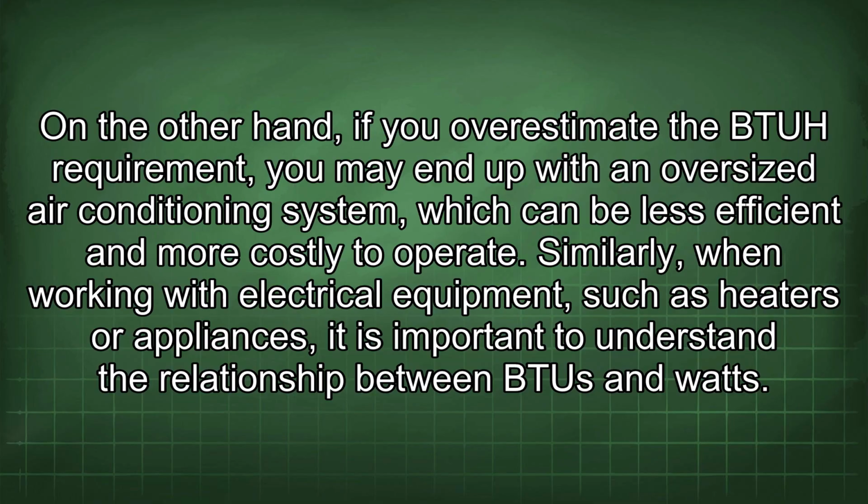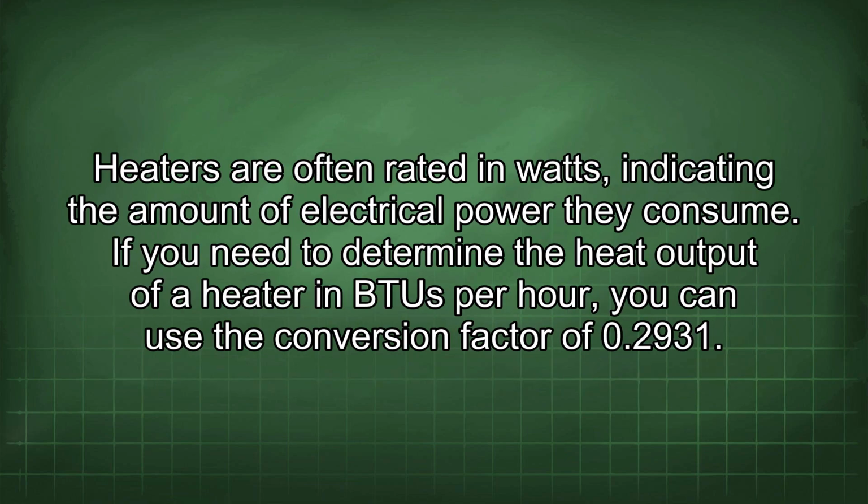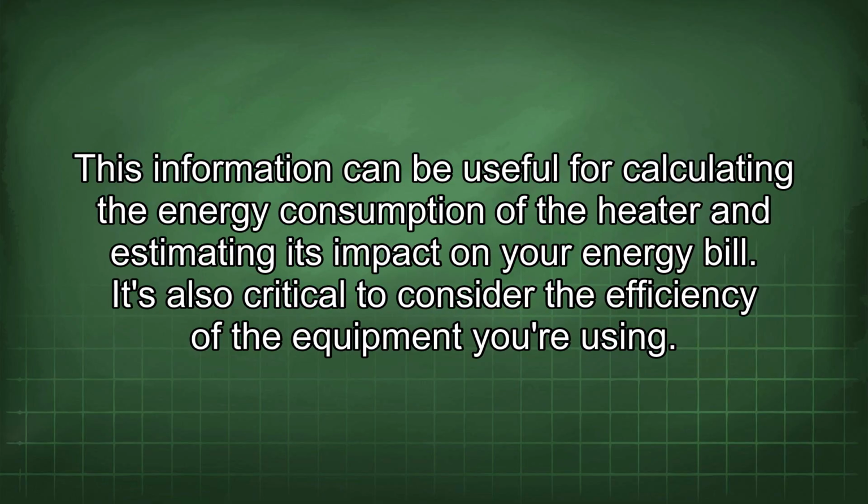Similarly, when working with electrical equipment, such as heaters or appliances, it is important to understand the relationship between BTU and watts. Heaters are often rated in watts, indicating the amount of electrical power they consume. If you need to determine the heat output of a heater in BTU per hour, you can use the conversion factor of 0.2931. This information can be useful for calculating the energy consumption of the heater and estimating its impact on your energy bill.